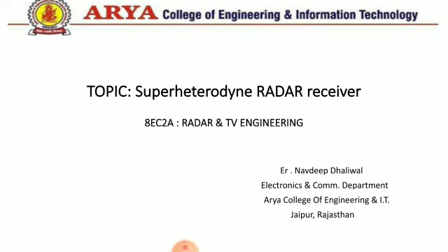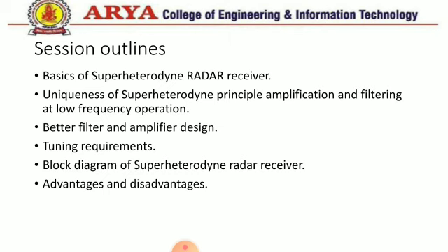So today we are going to understand the radar receiver used in the radar system. The most common receiver used in radar is the superheterodyne radar receiver. So these are my session outlines. First we will discuss the basics of the superheterodyne radar receiver, and then the uniqueness of the superheterodyne principle: amplification and filtering at low frequency operation.